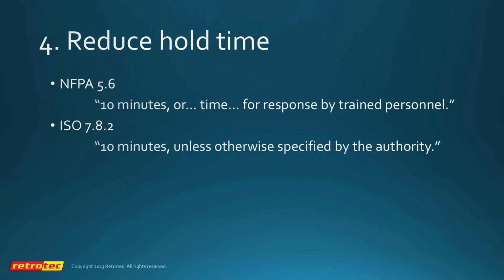Now, a reduced hold time might be appropriate for very small enclosures where there's not a lot of mass. They tend to be particularly difficult to pass the hold time evaluation. Small enclosures of, let's say, 10 square meters floor area and less are very difficult to pass because the volume is very small and there's a lot of surface area. There is no reason why we need a 10-minute hold time in those enclosures. It could be 2 minutes or 4 minutes or whatever. So that's something that does need to be considered.